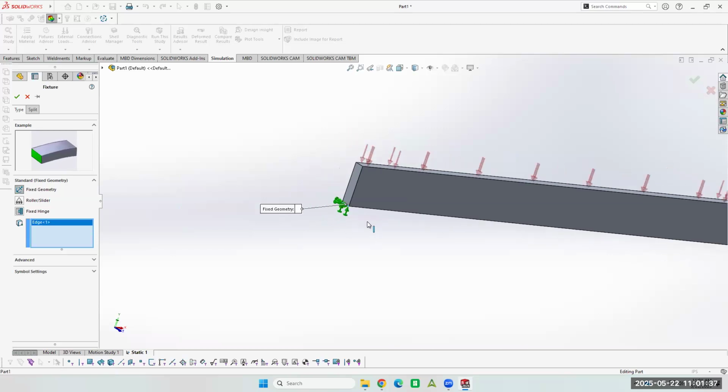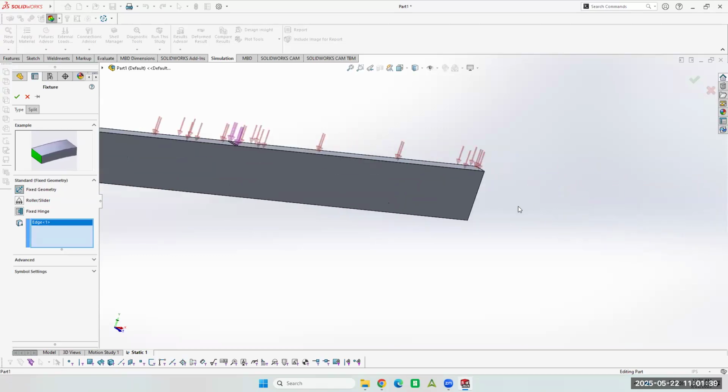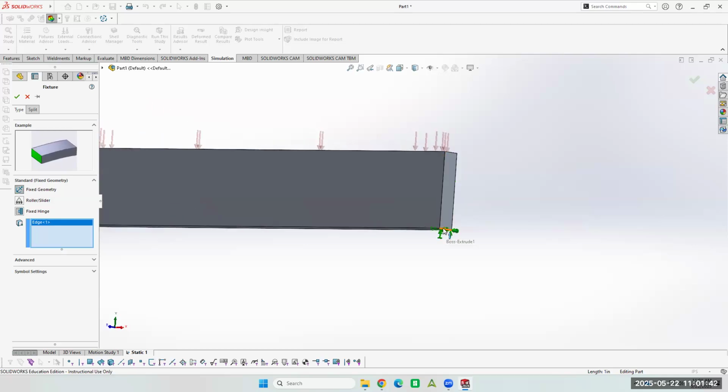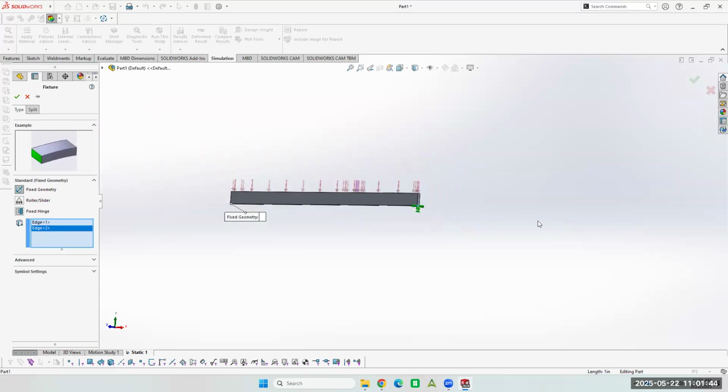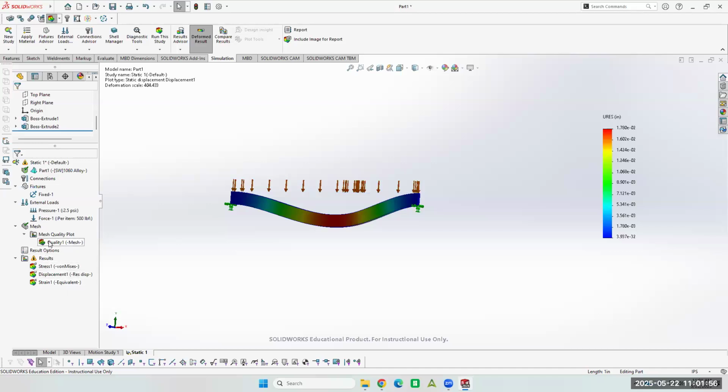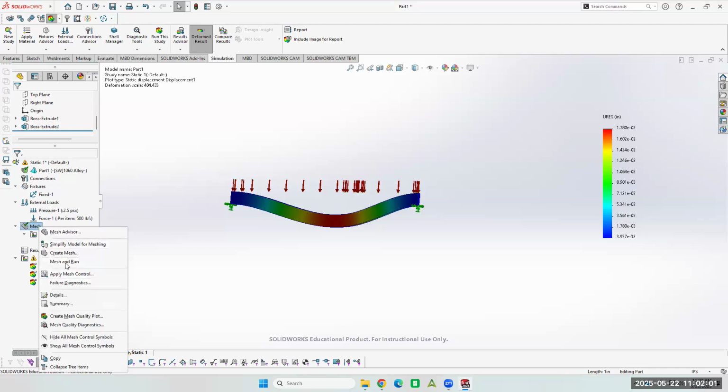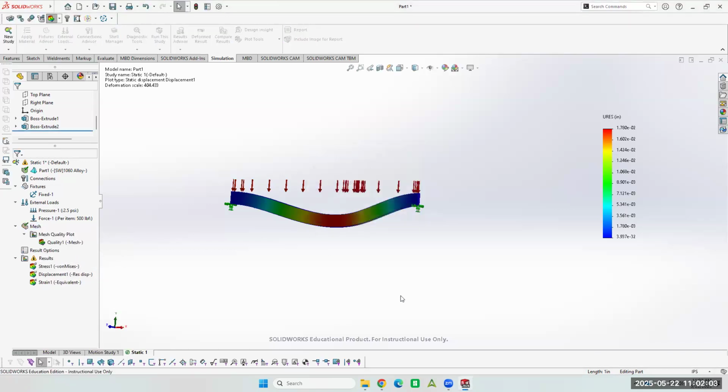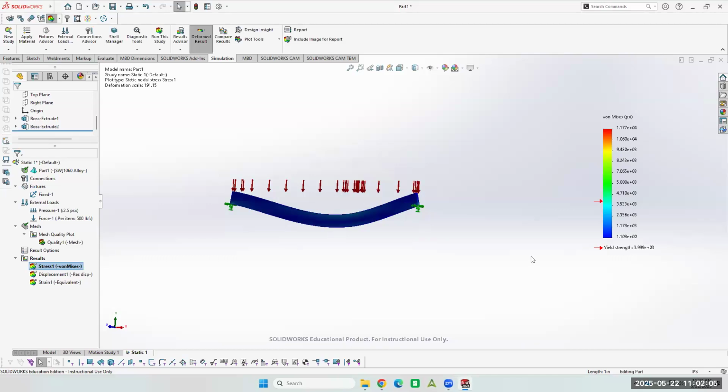Let's see if I can fix just an edge, because it's going to change the stresses if you allow it to rotate. Right now it's fixing that whole end, so it's not allowing end rotation. A pin and a roller allows end rotation. That's going to take a lot of stresses away. So let's do it this way. Oh, substantially different. Now we're down to only blue.